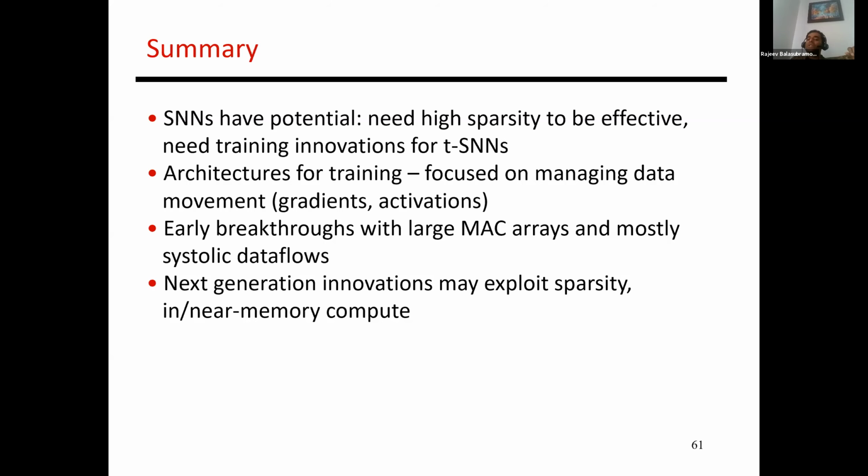And so the next generation hardware needs to look for other opportunities. And there is some low-hanging fruit by doing things like pruning, but then exploiting other approaches for sparsity may cost more. You may need new circuits for in-memory computing. That's another area that has some low-hanging fruit. We've seen that when you're designing chips for training, you need to focus on a good interconnect between the chips. You need to have a lot more memory so that you can save activation maps during the forward pass.